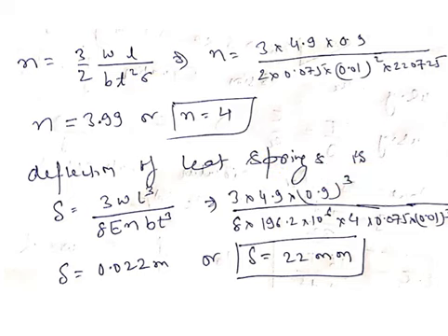Now we have substituted the value of all the given parameters, and then we have found that n to be approximately 3.99. So for having 3.99 blades, we will approximate it to 4. There should be 4 leaf spring blades available in this case.